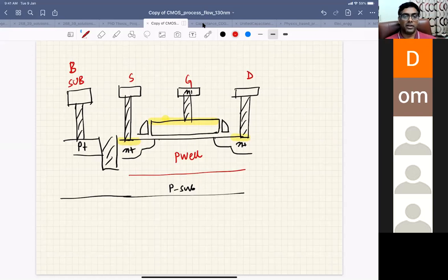So this is the typical transistor, and you just visualize this in your head. When I talk about a transistor, I have this structure, with all the contacts, source, gate, drain, and body, taken at the top. When I draw the schematic, I give a body contact, but because I cannot give a body contact inside the substrate, everything has to be at the top.